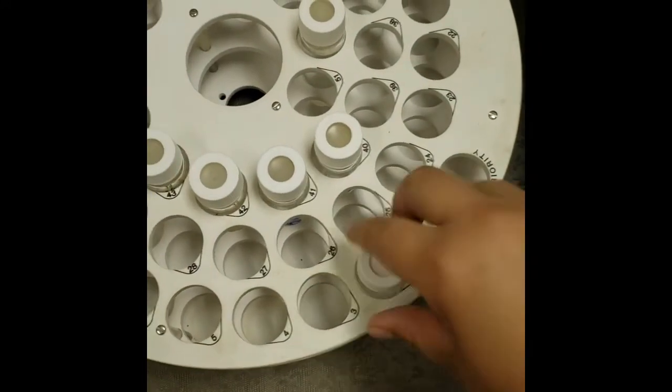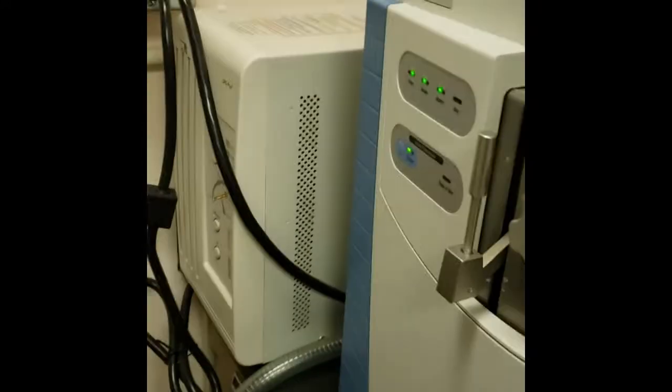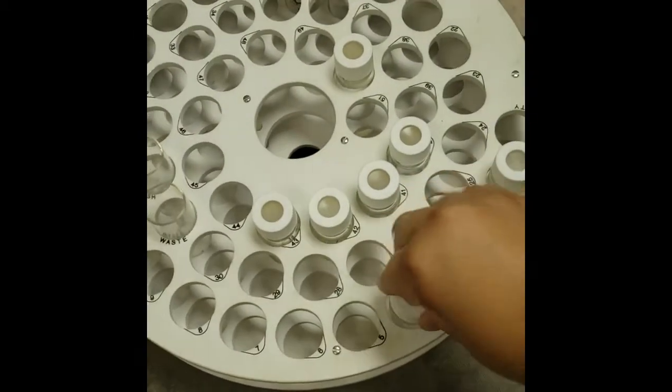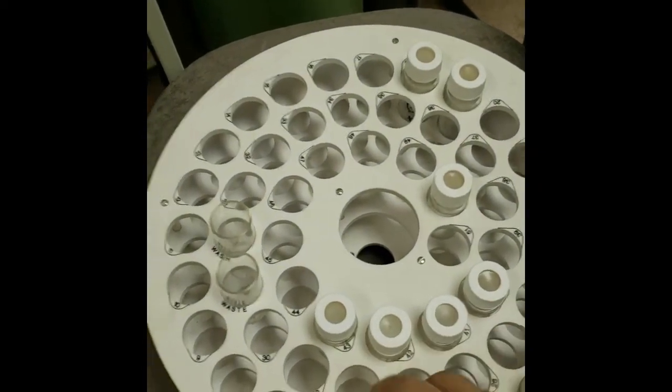So I will go ahead and grab my samples, and I'm going to run 2 blanks as 1 and 2. I will run my CCV, my check standard, as number 3. I'll run another blank as number 4. And I will then run my raw sample as number 5. And again, I'll just finish with a blank just to have a clean needle in case there's any contamination to